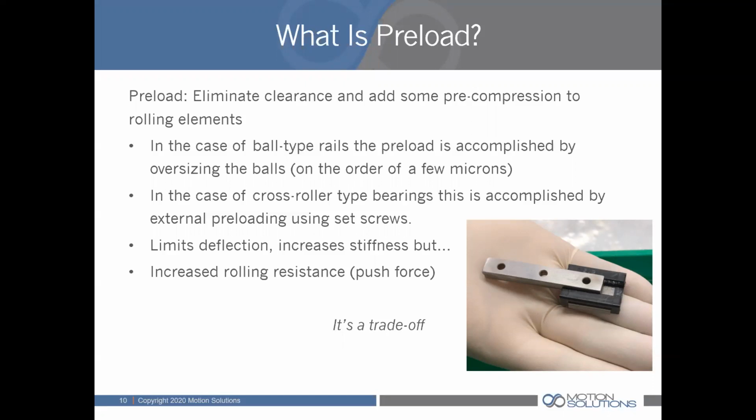Well, they have gauge balls in the nominal size of every ball size. In this case, we're talking about 1/8 balls, but in 1 micron increments. So they'll have 1/8 ball plus 1 micron, plus 2, all the way up to plus 20 microns or above, and minus 20 microns or above or below. By doing that, that's enough tolerance range such that they can take up their grinding tolerances and select the proper ball that results in the right fit of the bearing on the rail.